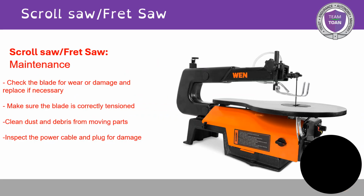So on here, I've got a few machines with their maintenance. A lot of them you can use for any machine, but there's a few extras that I put on there. So maintenance for scroll saw, fret saw, you check the blade for wear or damage and replace if necessary. Make sure the blade is correctly tensioned. Clean dust and debris from moving parts. Inspect the power cable and plug for damage. You can do that for every single machine.